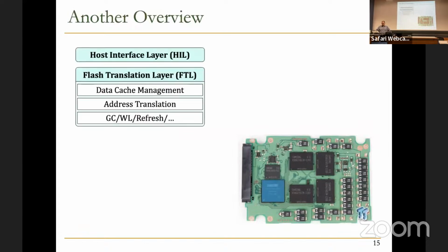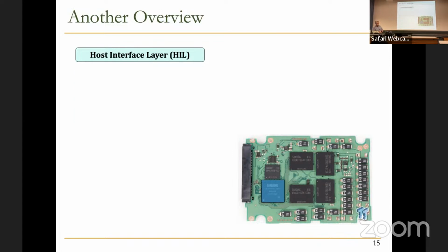For the SSD controller, there are different components or steps that we need to handle. One of the first is the host interface layer, HIL, whose goal is to implement the interface protocol, like SATA, and also NVMe that we have today. That's the job of the host interface layer: to provide an interface such that the host system, like the CPU, can communicate with the storage device.